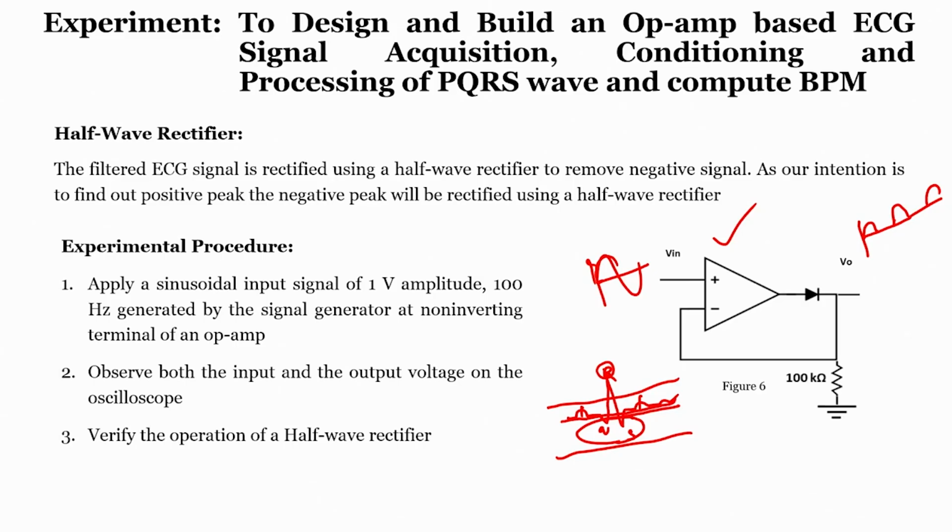That is the reason, as we already know that the QRS peak is very long, having a very high amplitude compared to other peaks. If we can detect this particular peak, our problem is solved. So, in order to detect that, we are using a capacitor which stores the complete highest voltage, but how do we create a threshold? If I can create a threshold and compare the output signal with the input signal, whichever is the highest, I can decide it.